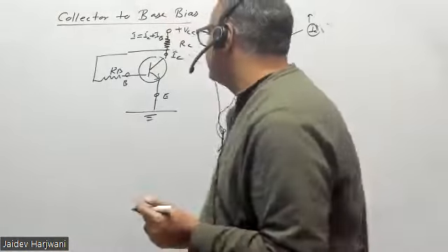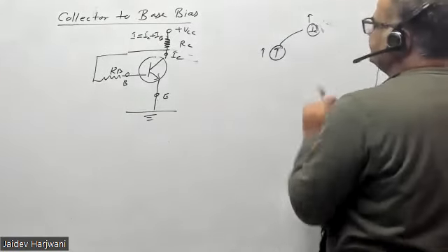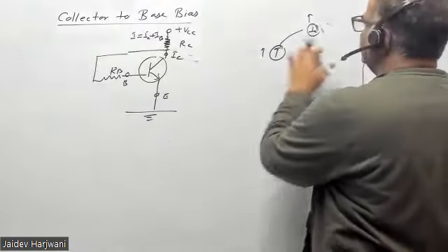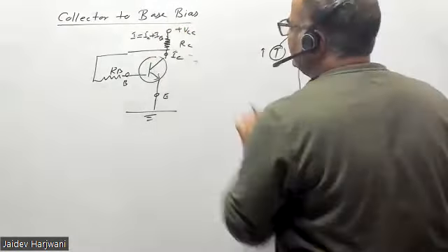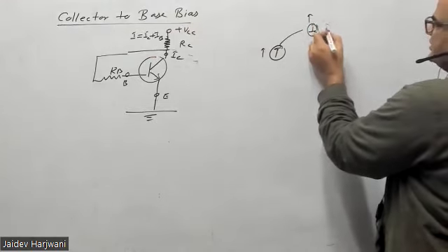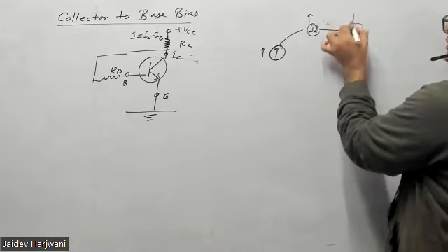Correct, correct, correct. So now your temperature is increasing. Temperature is changing IC, IC increasing. Then this drop across resistance, because this is IC plus IB, is also increasing. So VRC also gets increased.